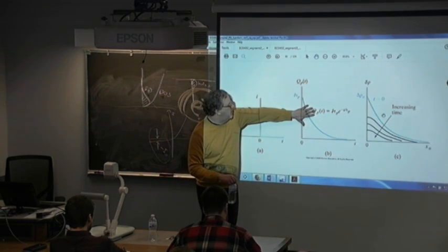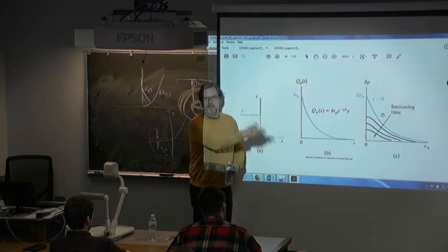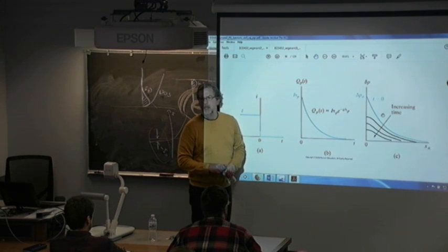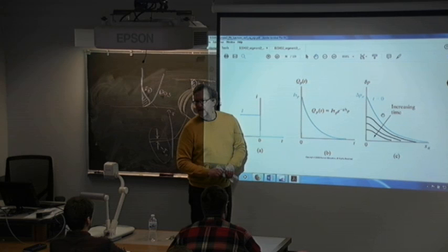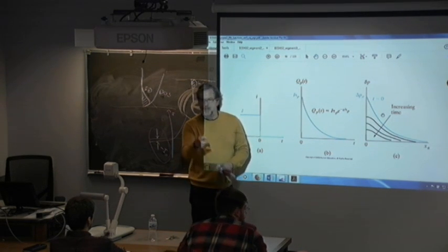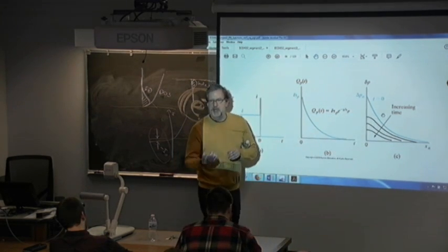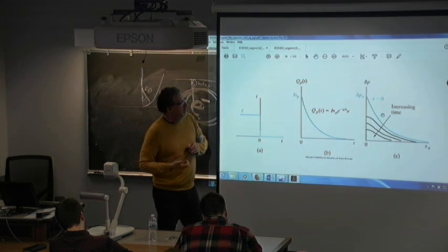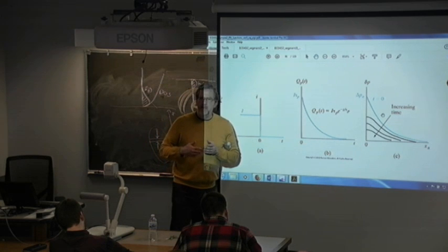And how is this excess charge going to disappear? Is it going to go to the other side? No, it's not going to diffuse. Does it recombine? It's going to recombine. So it's slowly recombining. So you're sitting there with your stopwatch and you're waiting, and instead of diffusion length, you think about it as recombination time.